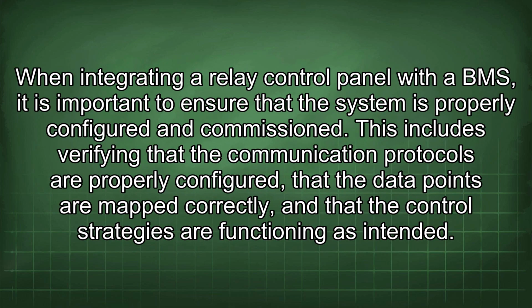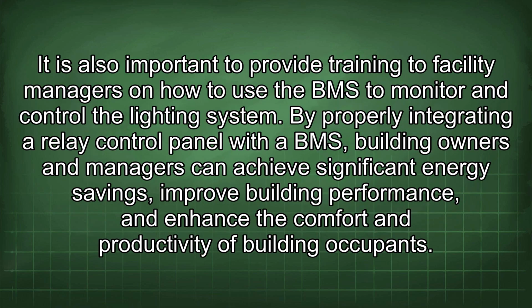When integrating a relay control panel with a BMS, it is important to ensure that the system is properly configured and commissioned. This includes verifying that the communication protocols are properly configured, that the data points are mapped correctly, and that the control strategies are functioning as intended. It is also important to provide training to facility managers on how to use the BMS to monitor and control the lighting system. By properly integrating a relay control panel with a BMS, building owners and managers can achieve significant energy savings, improve building performance, and enhance the comfort and productivity of building occupants.